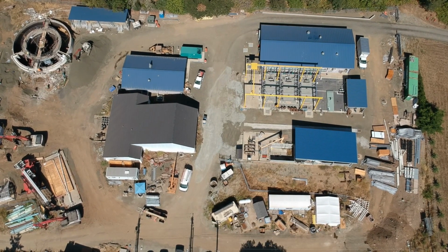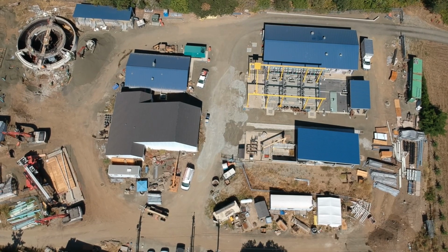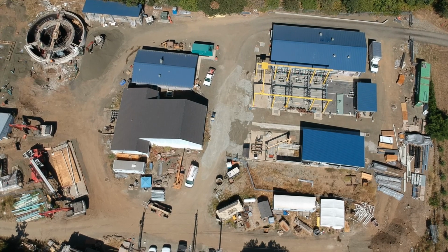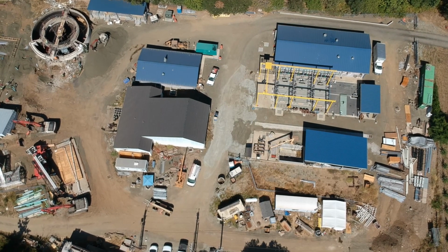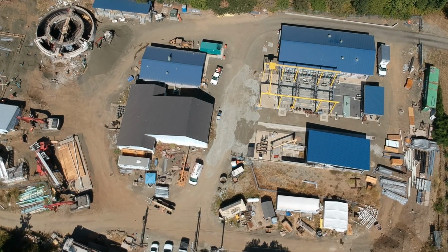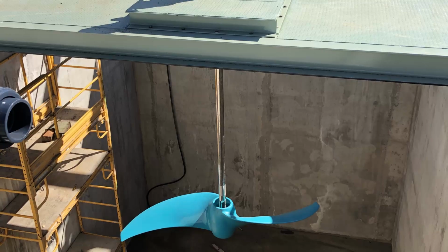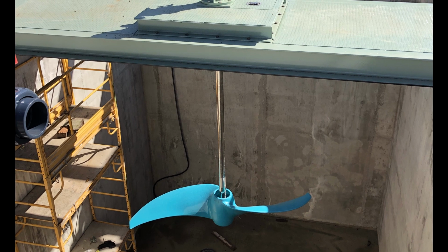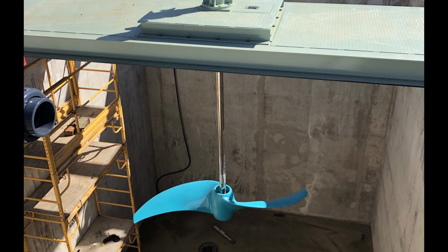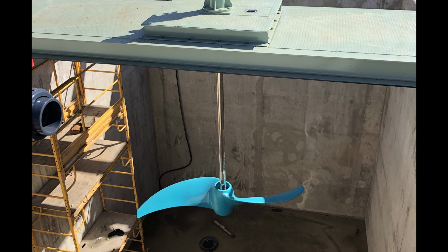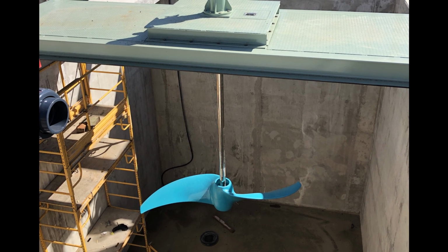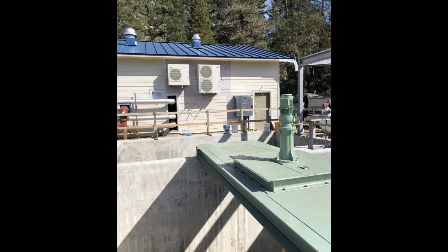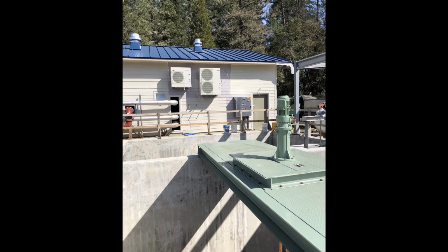This is helpful to reduce the possibility of dropping the system's pH. The nitrification process is optimized with a pH of approximately 7.5. Nitrifiers have diminished kinetics at lower pH values. We do have the ability, if needed, to add alkalinity to the Inoxic tank. A small duplex chemical feed package in the chemical room is installed to feed alkalinity into the system if the pH value drops due to nitrification rates and low influent pH alkalinity values.